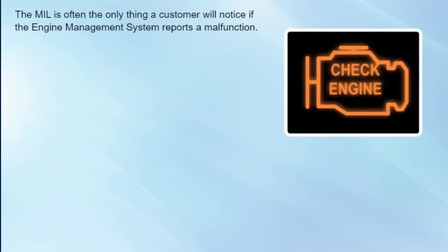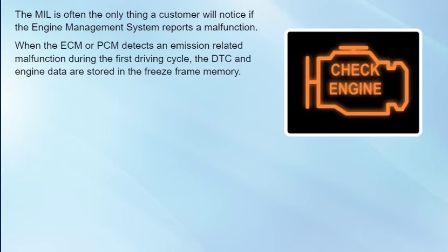The MIL is often the only thing a customer will notice if the engine management system reports a malfunction. When the ECM or PCM detects an emission-related malfunction during the first driving cycle, the DTC and engine data are stored in the freeze frame memory.